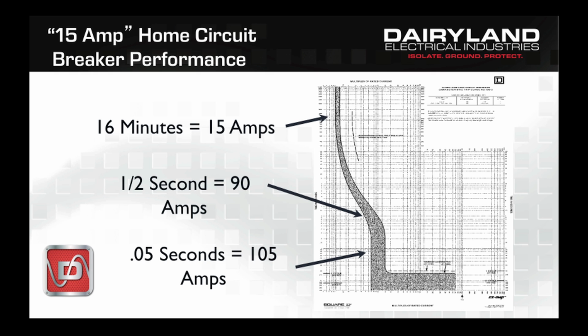If we go to a slightly longer time, say a half second, that circuit breaker would trip at 90 amps. Finally, if we really draw that time out to 16 minutes, the circuit breaker would trip at 15 amps, its actual rated current.